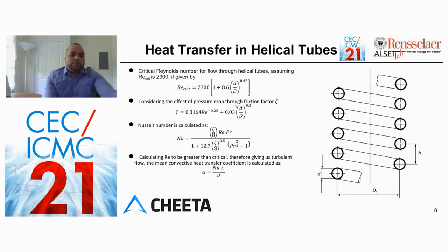This is a function of the diameter of the coil, that's small d, and the diameter of curvature of the entire pipe, that's capital D. If this value exceeds 2300, the flow is turbulent, and based on the geometry of our current design, the flow regime is turbulent. Next, the effect of friction is considered through the factor zeta, which is a function of the Reynolds number Re, the diameter of the coil small d, and the diameter of curvature of the pipe, that's capital D.